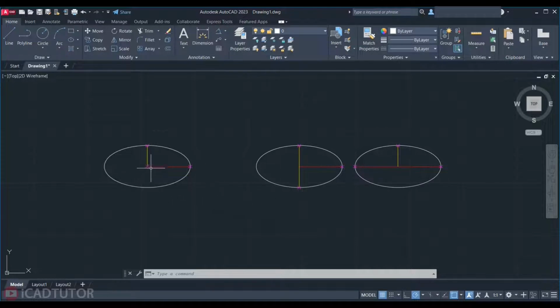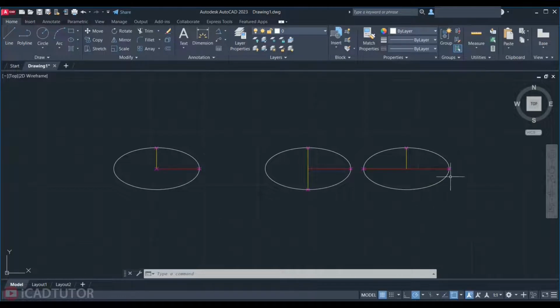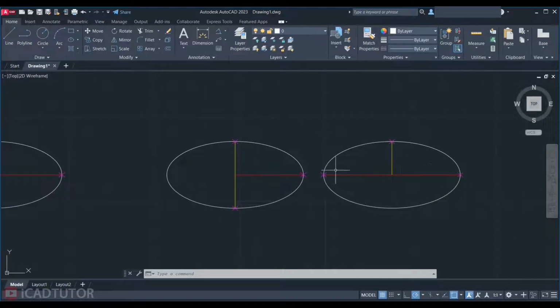Like drawing a circle, one of the most important ways to draw an ellipse is to use the center of the ellipse and the radius. The difference is that an ellipse has two radii, a longer one and a shorter one. Well, it's the first method. In the second method, we draw an ellipse that passes through 3 points. Using 2 points, the length of one of the diameters will be determined, and using the third point, the radius will be determined.